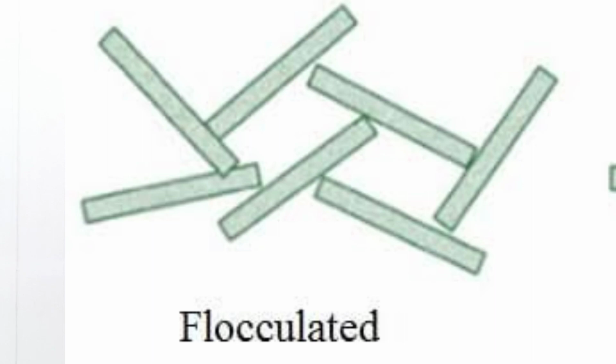And last is improved stone. Improved stone uses the same temperature as we already used in the previous calcination plus addition of 30% calcium and magnesium chloride in the gypsum. These are basically deflocculants and increase the density of the material and separate the particles, avoid agglomerates of the particles.